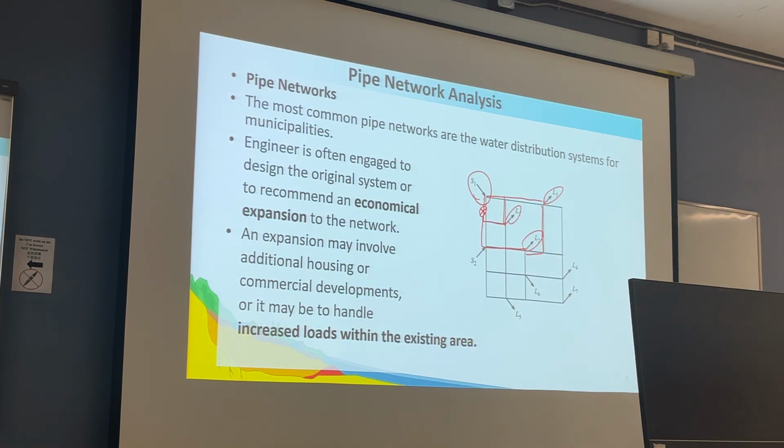There will be many settlements inside the pipe that will increase the head loss and also reduce the flow. Sometimes they may need to be replaced. Another situation is that at a certain time there will be more estates or more users built in a developing area.